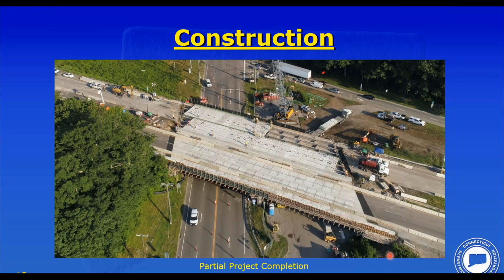So you see in the photo here, you can see these trapezoidal pieces at the end were done with cast in place. That's one of the issues with longitudinal post tensioning. The detailing of these end panels, if they're skewed, gets very complicated. This is why I mentioned before about UHPC might be something we would consider today. You can go with trapezoidal shaped panels because you don't have those anchorage assemblies for the longitudinal PT.